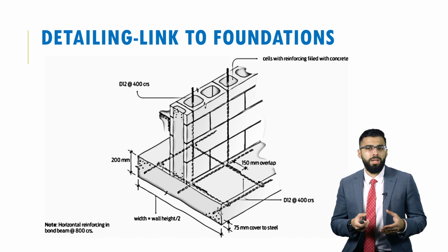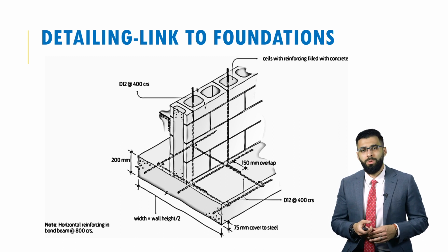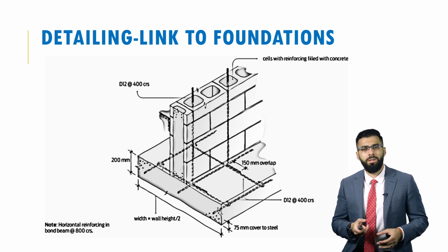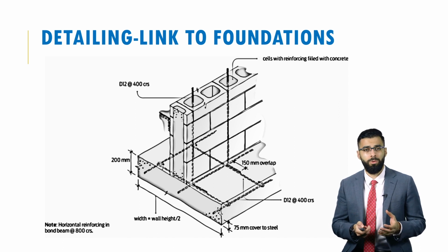The core that you see in a masonry unit is actually empty. So you place your steel rod in it, and then you have to fill it with grout in order to make sure that the reinforcement becomes part of the overall structure.